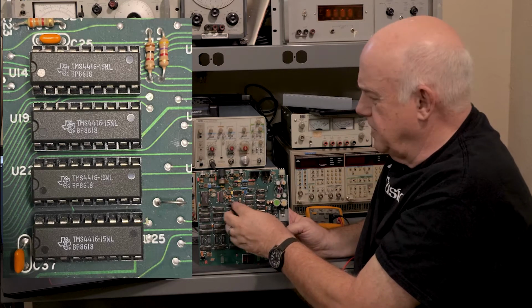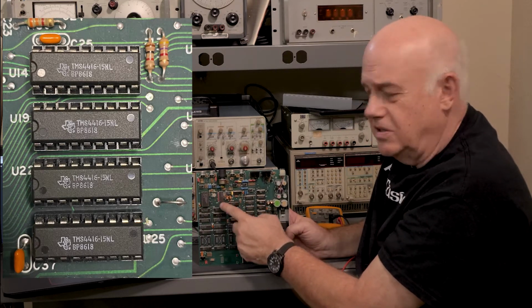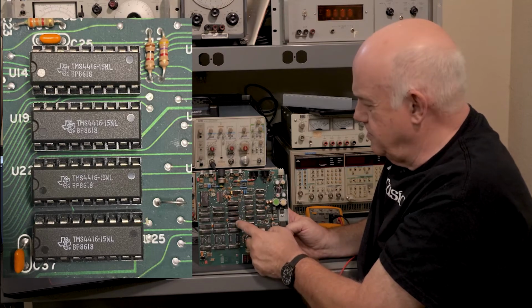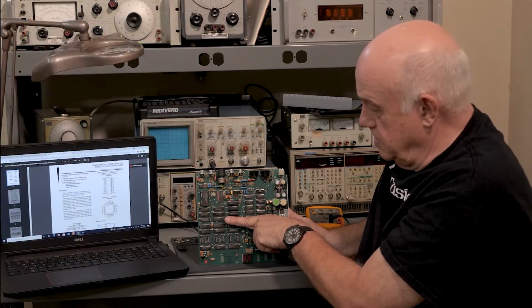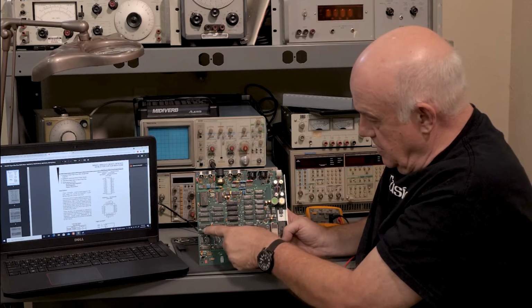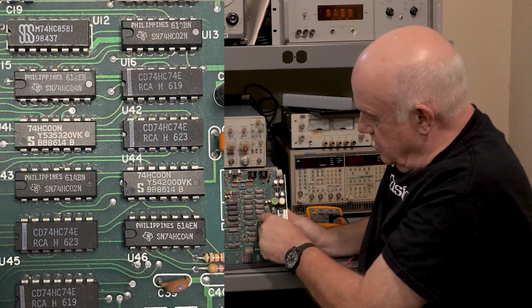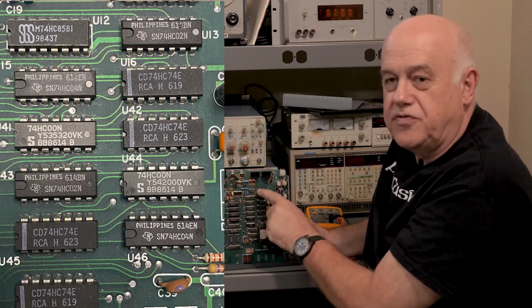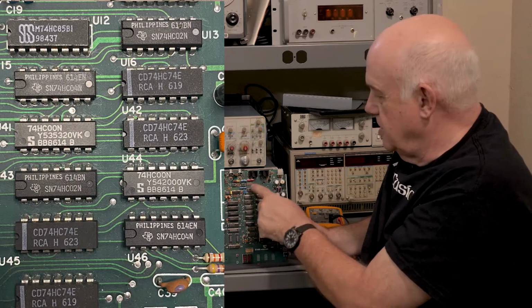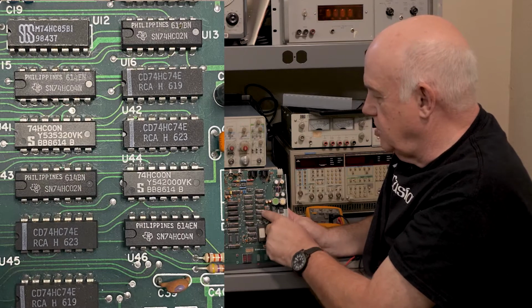That's unusual because it's only a 12-bit converter. Why do you need a 16-bit memory? Why don't you just do that? Save yourself a chip. Over here, nothing is octal. This is all just inverters and flip-flops and NAND gates, what we call combinatorial control logic.